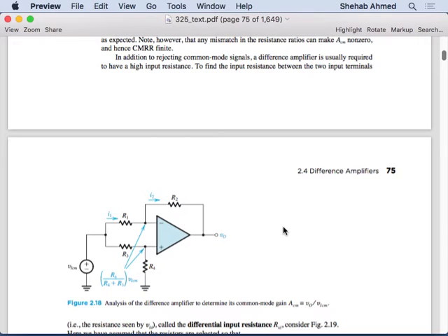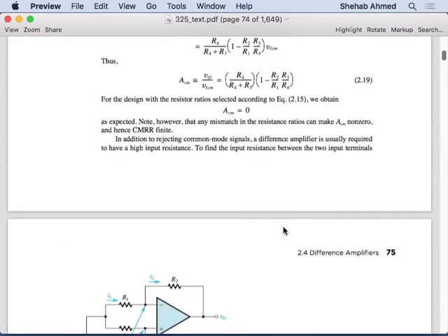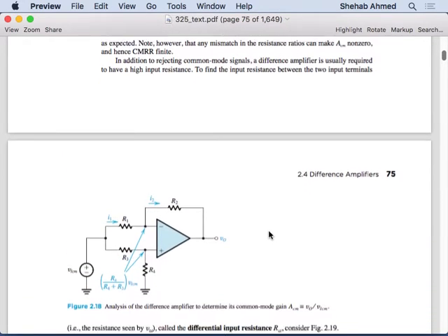And then the resistance values change with temperature, right? So it's a messy process here. So there is gain to common mode unless these resistors are perfectly matched, which is a problem.